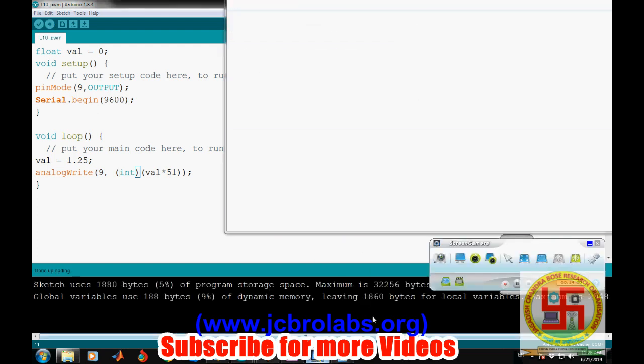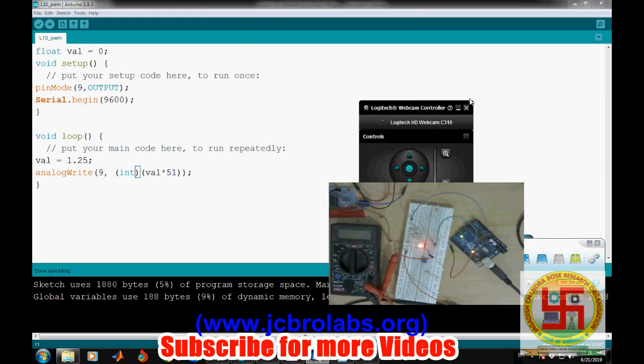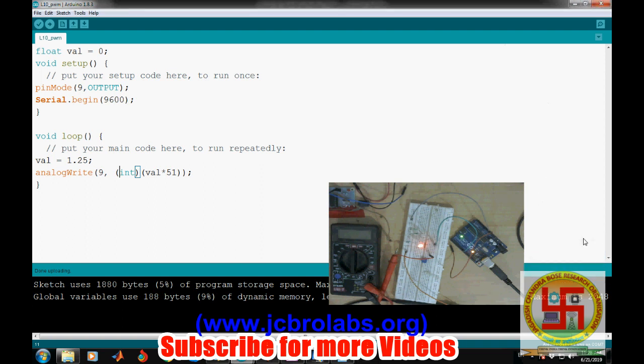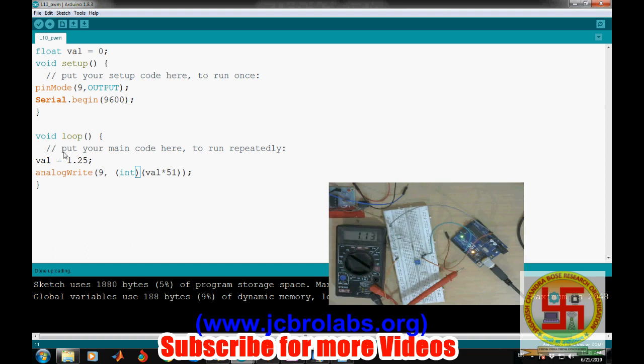Now let's have a look at the hardware. This is our hardware, this is the multimeter, and this is pin number 9. Now we are connecting pin number 9 to the multimeter pin so that we can check the value. We wanted to generate 1.25 volt, and it's generating nearly 1.23 volt. Okay, let's change it to 2.25 and see whether it is able to generate the value of 2.25 or not.